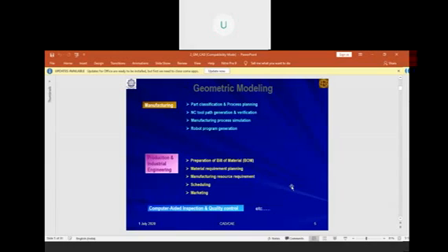You already know that additive manufacturing and 3D printing is such a disruptive, cutting-edge manufacturing technology, which will work only if you feed it the geometric model. Without the geometric model, it will not work. Other machines can work based on your 2D drawing and by writing G and M code. You can also generate the toolpath, but for additive manufacturing you need the geometric model.